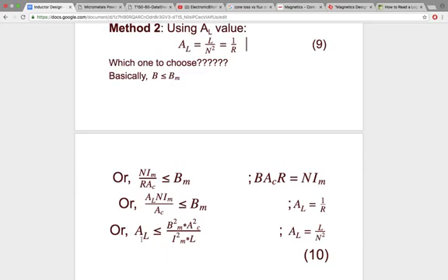And if this is satisfied, you will see that this is lower than the permeance. That means the reluctance of the core is already greater than the reluctance required. So in this case, there is no problem. The reluctance of the core should not be lesser than the reluctance required, but it can be greater, and that will not create a problem.